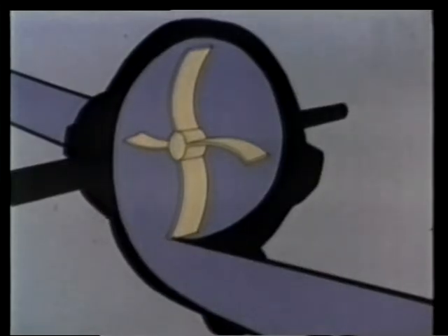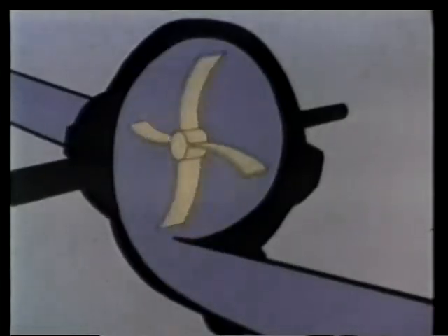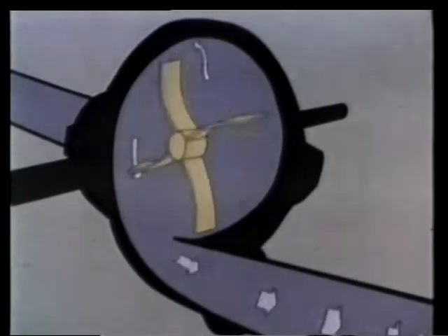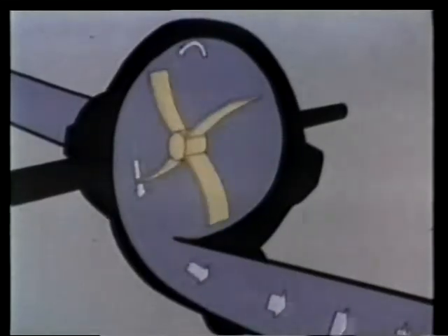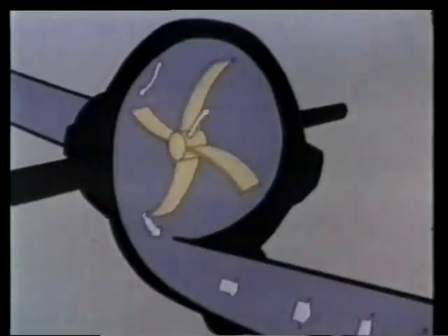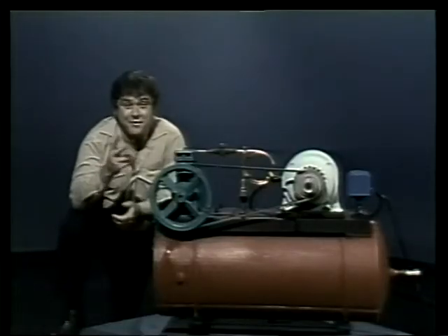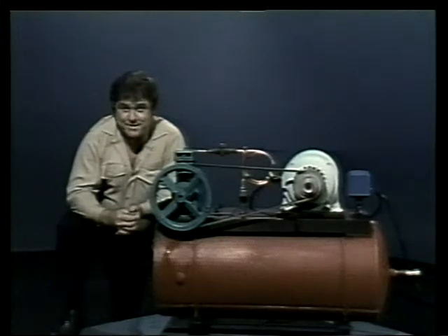Dynamic compressors work differently. Now, this centrifugal compressor is one example. It has an impeller that draws air into the casing and accelerates it by slinging it out towards the tips of the vanes. This fast-moving air is pressurized when it slows down on the discharge end. Those are the 2 general types of compressors: positive displacement and dynamic.